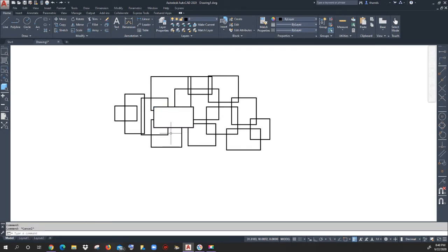Now let me show you how I trim. I'm going to click the trim command, and anywhere in my drawing, I'm going to right mouse click. That made everything a cutting edge. Notice my command advanced. So now anything I pick can be trimmed away because I told it all to be a cutting edge.